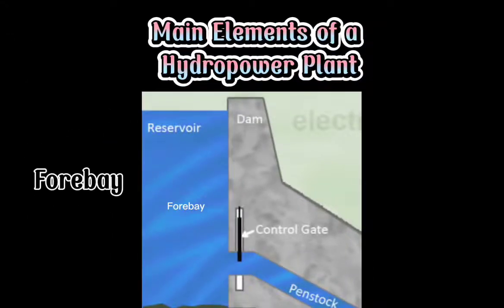Next is forebay. The forebay functions as a control reservoir, temporarily storing water during the periods of low load and providing the same for initial increases due to rising load, during which time water in the canal is accelerated.